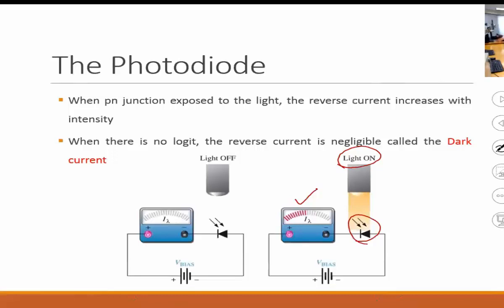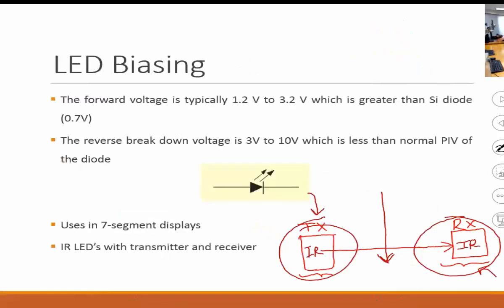For example, remember previously I had a transmitter and receiver. I cannot have any type of IR transmitter and any type of IR receiver. There is something called a wavelength, in nanometers, and that wavelength should be in the range. For example, if the transmitter has an 800 nanometer wavelength and the receiver is designed for capturing 1000 nanometers, it's not going to work.